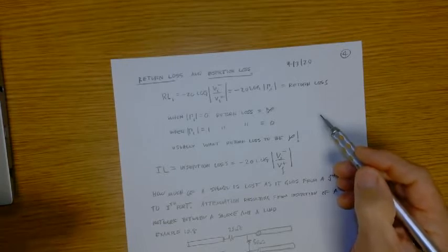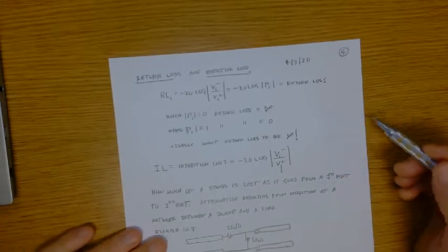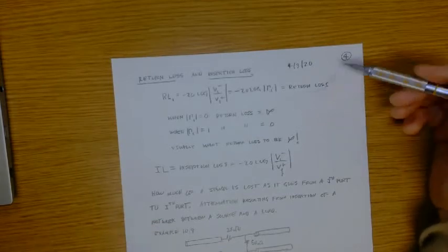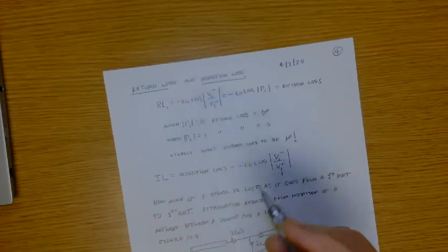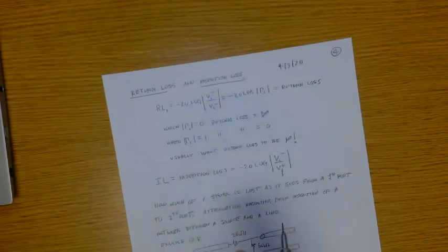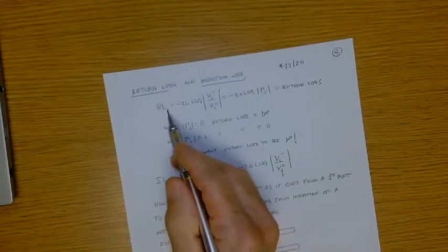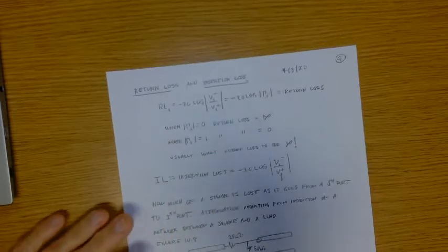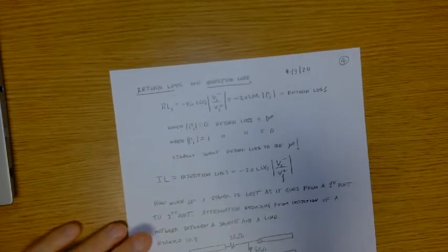So very often when you're analyzing antennas, you'll use a network analyzer and you'll measure S11, say, the input reflection coefficient looking into your antenna, and you'll express that as a return loss. It would just be a menu where you punch a button and then hit magnitude or hit dB, and it would express it in return loss as a function of frequency.